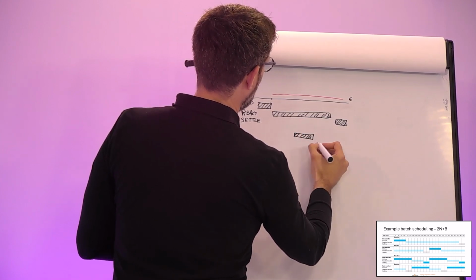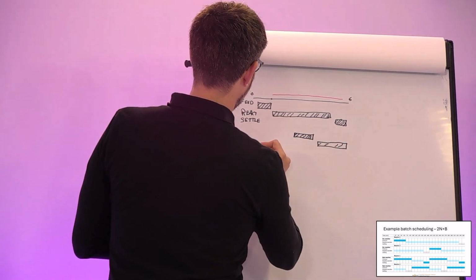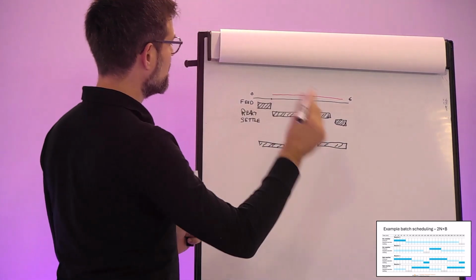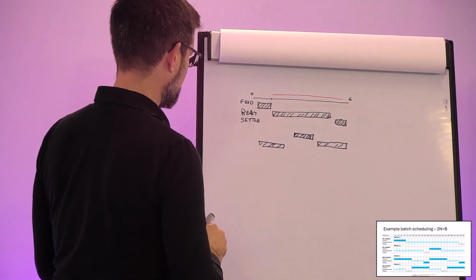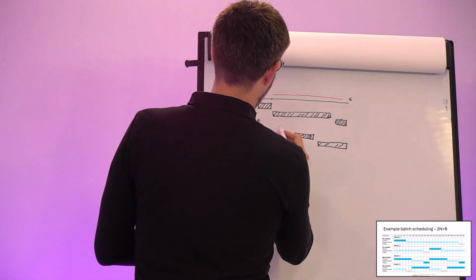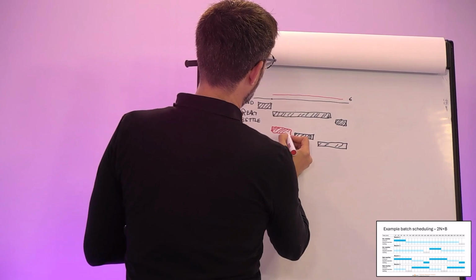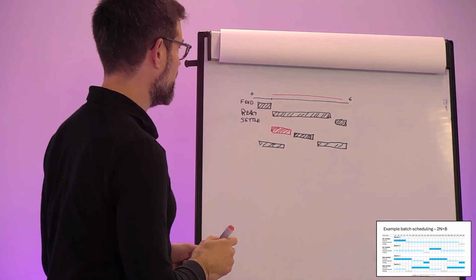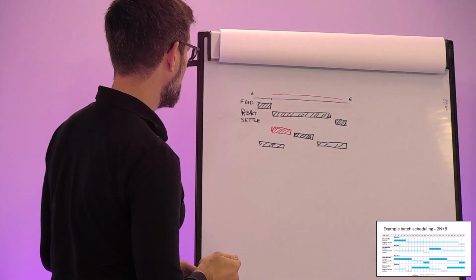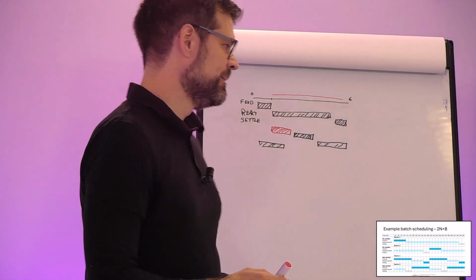And then you also get a reaction phase there. And that will continue in the next cycle compared to this. So it will continue on and on and on with the cycles between the reactors. But in this case, we have a mismatch in the feeding phase, like so. So in this period, we are not feeding because we have two reactors. And then we need a buffer to still put the influent somewhere. And this would be a general setup for dry weather conditions.